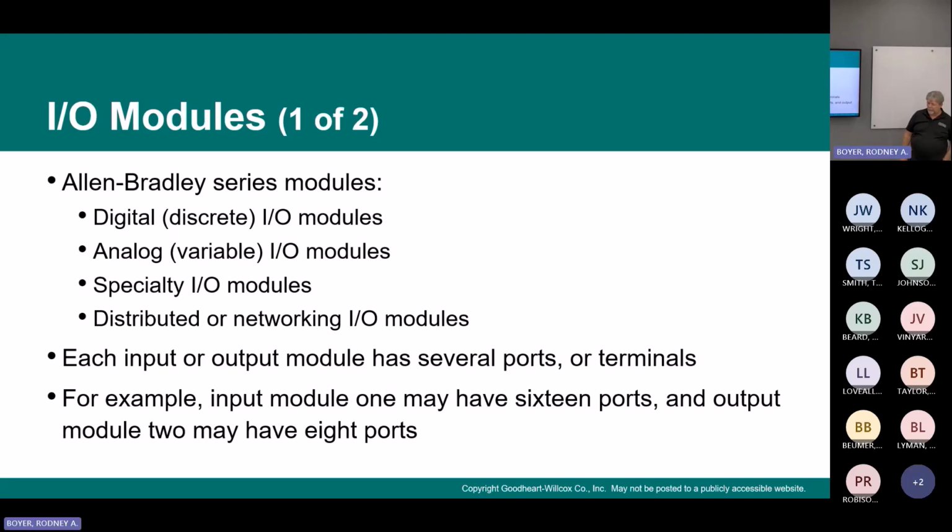Allen-Bradley series modules: digital or discrete I/O. You guys remember what discrete is? On or off. Analog is between a minimum and a maximum value. It can be anywhere in between.